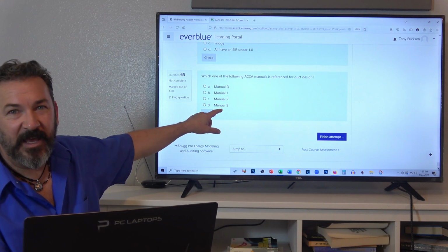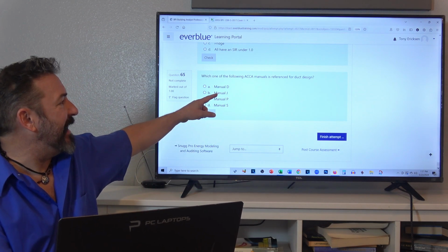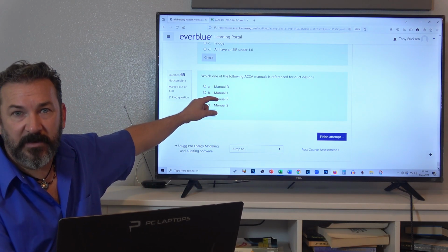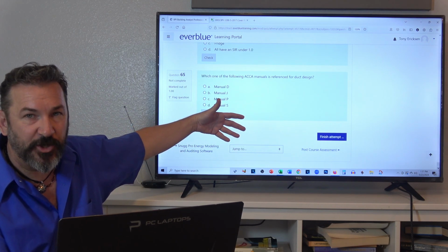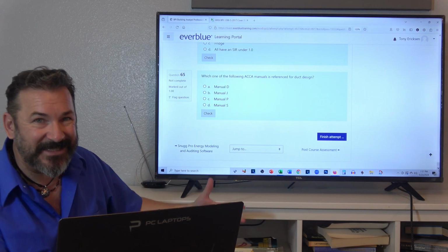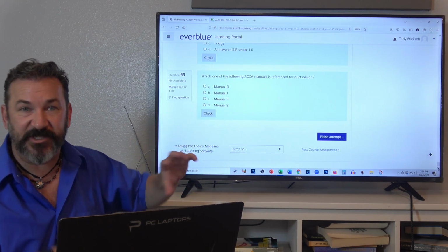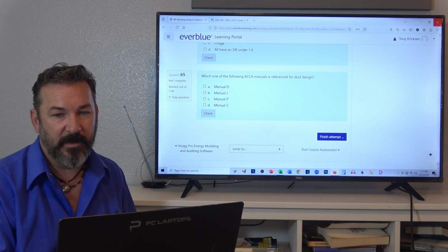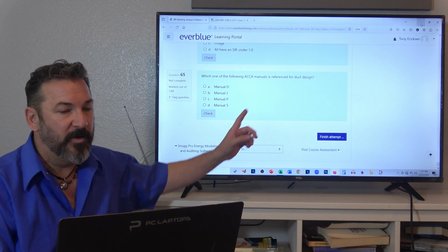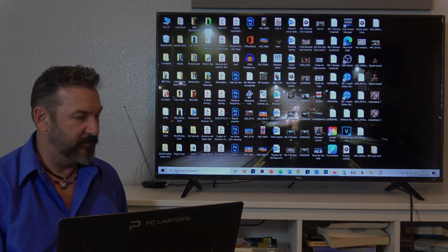I think that's real. S is equipment selection. So this is for sizing your equipment. Manual J is your heat loss calculation to size your equipment. Manual D is for duct sizing based on the equipment, and S is for specific equipment selection. And what is it asking for? Duct design. J is loads. D is duct design. J is your loads.